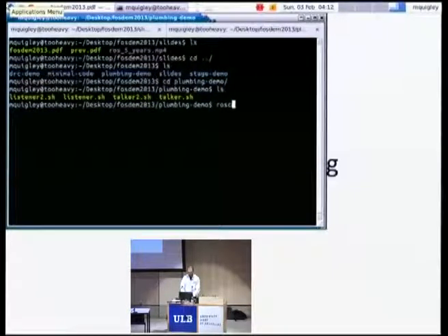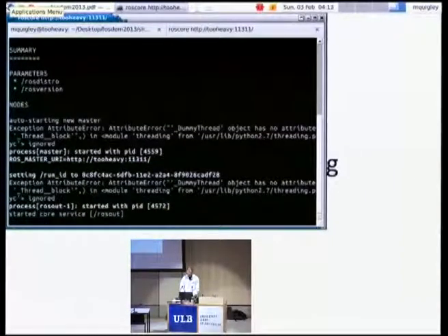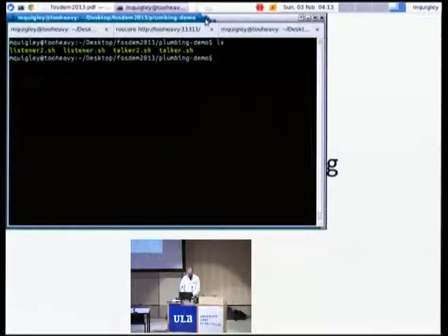Okay, so the first thing we start in a ROS system is called ROS core. It actually used to be called bot herder, and then a large defense contractor wrote us an email and said, you know, ROS is fun, but please don't call it bot herder. Our security people don't like seeing things called bot herder in our networks, sending and receiving data to random sockets. So now it's called ROS core. That just sits in the back. That's the master program that's running on top. You think of it like DNS. So that's going to just sit there and run the whole time.